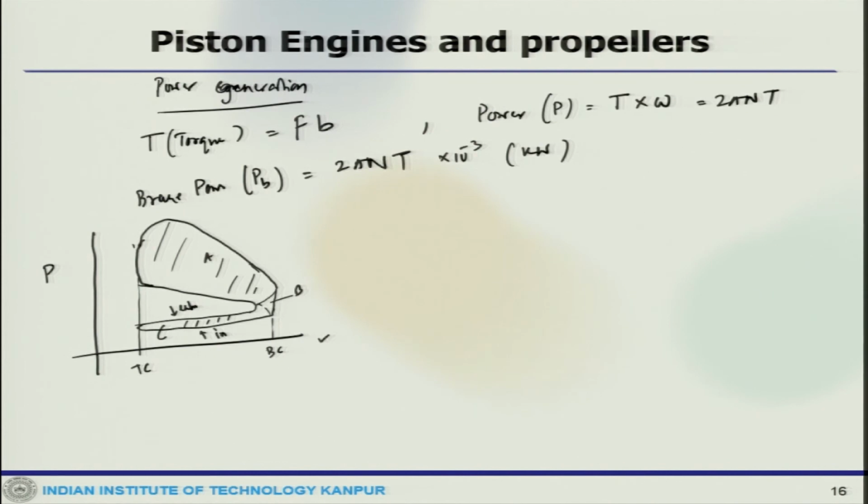So, you can see how the power is the indicated work per cycle per cylinder WCI, which will be PdV, and the net indicated work per cycle of the cylinder, which is area A minus area B. Then the power per cylinder is related to the indicated power.